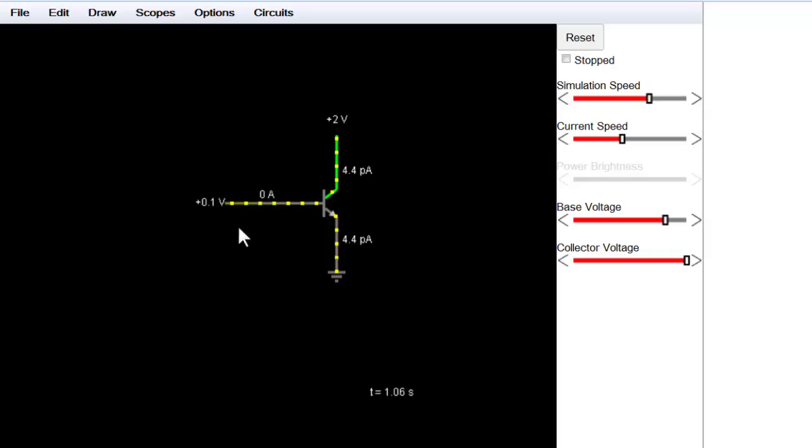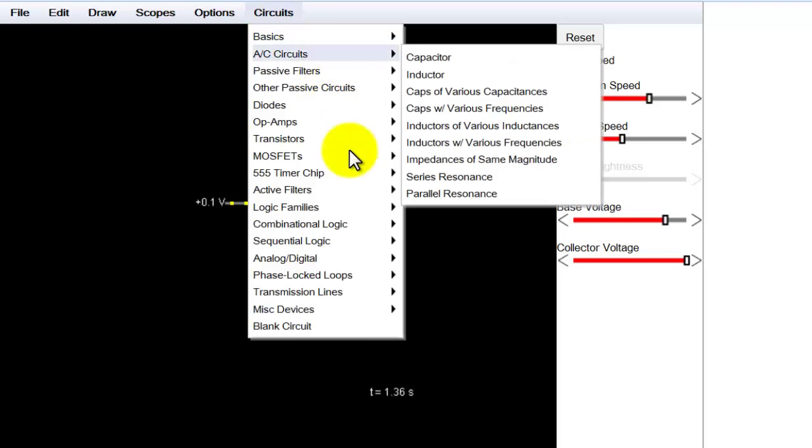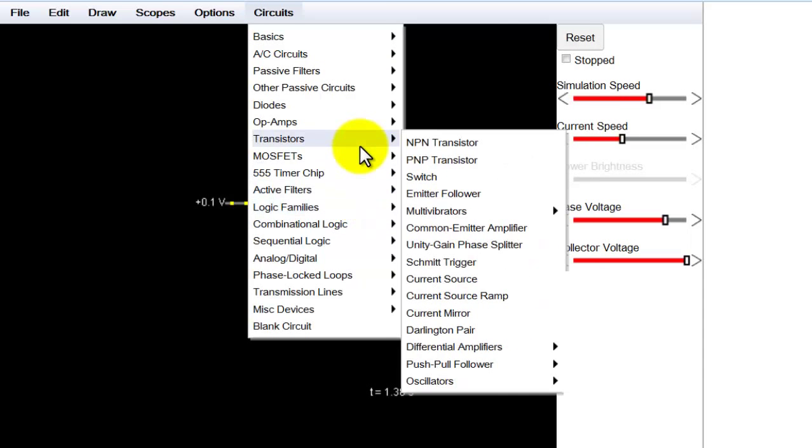So this can be operated as an electronic switch with the help of a microcontroller, and the controlling logic can be given by the microcontroller, while the supply that needs to be given to our device, depending upon the controller logic, can be given through the collector or through the emitter. There are various configurations in which this can be done, like the common collector configuration or the emitter follower configuration. So now let us actually see a PNP transistor.